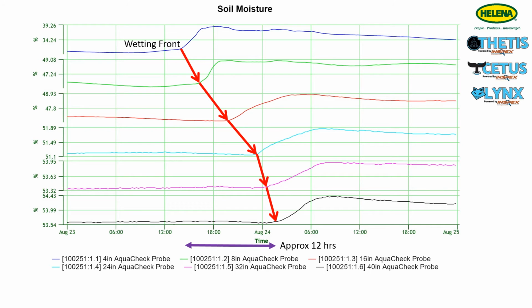By definition, field capacity is the amount of water a soil will hold after it has been saturated and allowed to drain for 24 hours. By observing the irrigation event and the beginning of free drainage, we can estimate field capacity approximately 24 hours later. This works reasonably well with surface sensors but may not hold true with the deeper sensors since we are unsure whether the soil was ever fully saturated before free drainage began to occur.